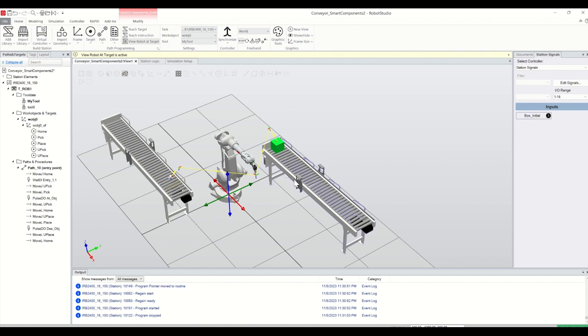The next step I'm going to do is use another linear mover for conveyor 2, and another plane sensor on top of this one, so that once the object is on top of this conveyor, it will start moving. And once this object touches the plane sensor, it will stop. And that's how we can make a full cycle, right?